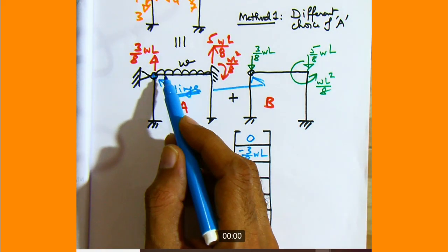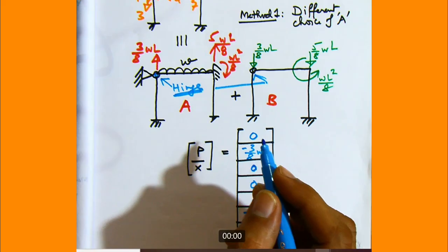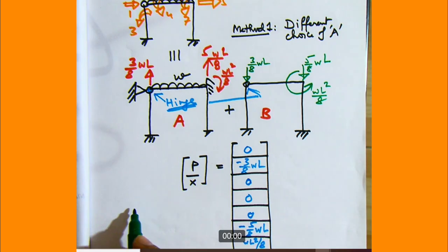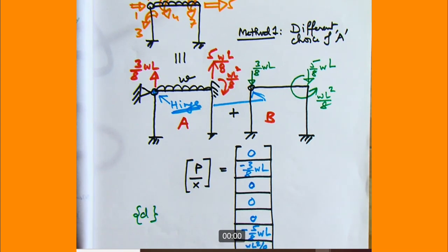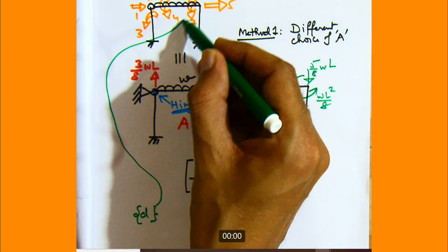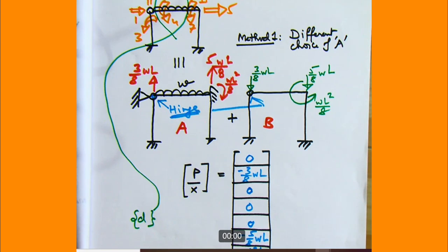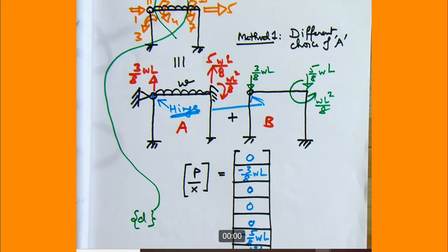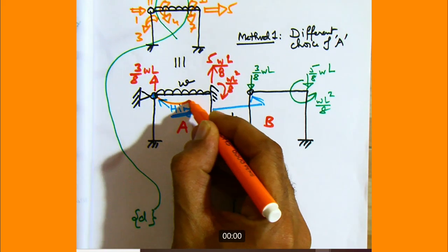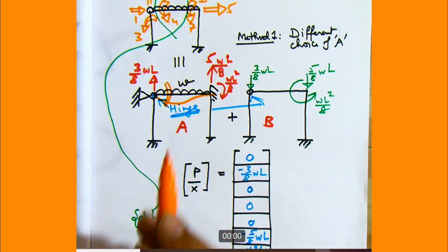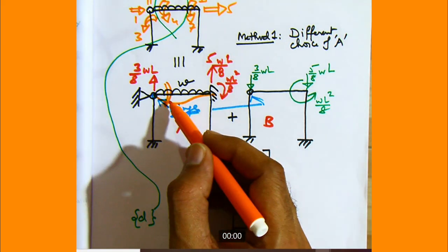But then when we do correction, in the end when we get the displacements and member end forces, we'll first get D. This D will include all the displacements, including this rotation also. But then we have to apply correction here also, because in this particular case the structure is deforming like this, it's undergoing deformation like this. So we have to apply this correction for this fixed ended case rotation. This has to be done in the end, that we need to do displacement correction also.